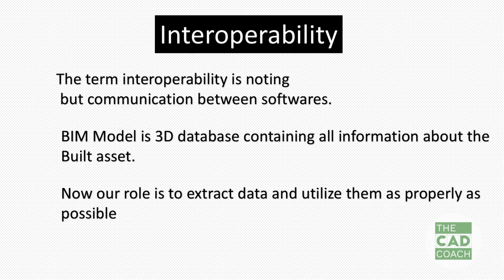For example, the BIM authoring tool Revit communicates with Navisworks, and the Revit 3D model goes to Navisworks. Navisworks does the clash detection, stores the clashes and sends the details back to Revit. The engineering team works on the Revit model and resolves the clashes, then sends the Revit model to Navisworks again. They do clash detection again, and this goes to and fro until a clash-free model is created in Revit. Now a beautiful project model is available in the BIM authoring tool, Revit.